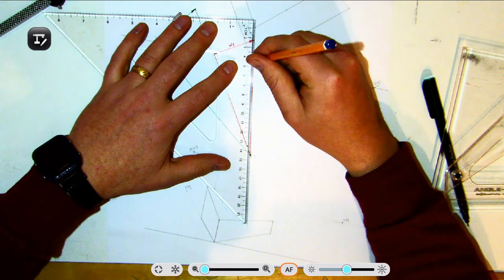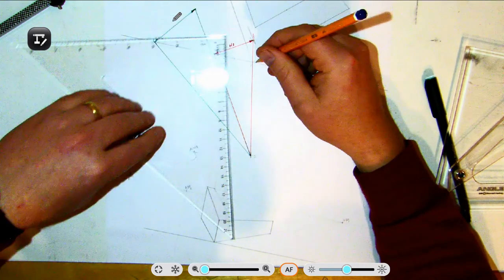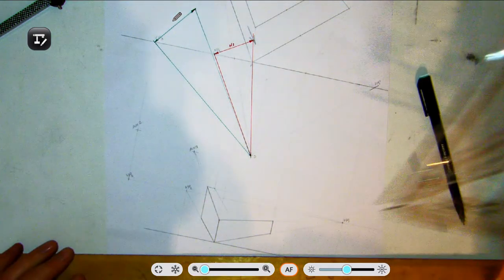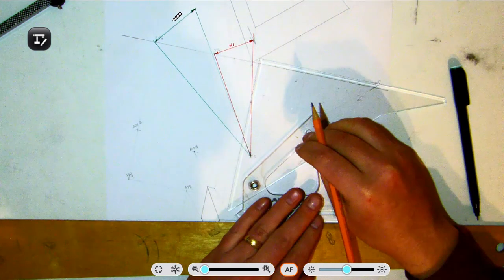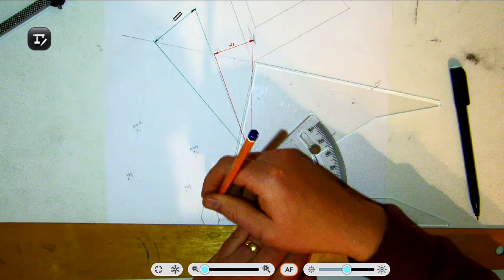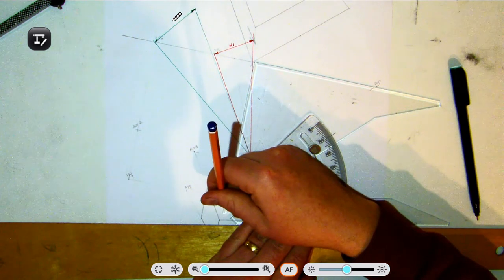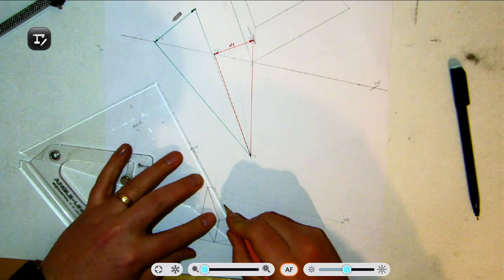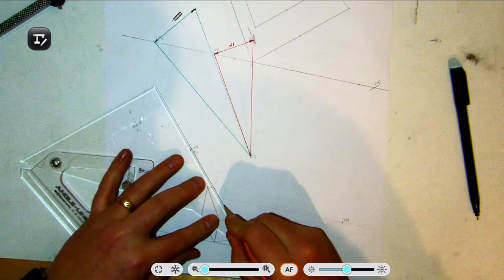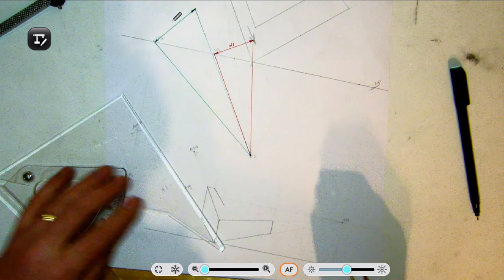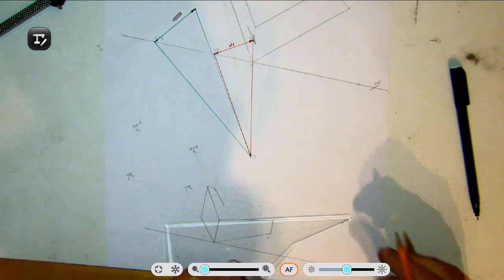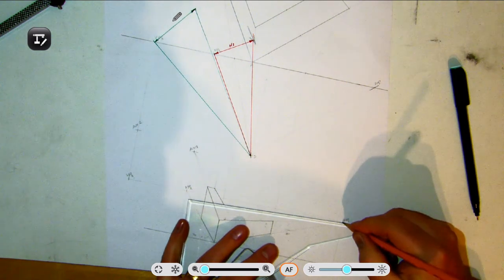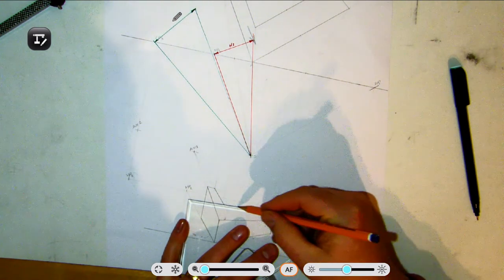Now when we have that done, we can find on our picture plane this point from plan. So find this on your picture plane. So this point here now is brought down, marked off here, and what this has given us now is this side edge here. Now what we can do with this then, we know the front edge of the building here is horizontal, so this is joined back to VP1.